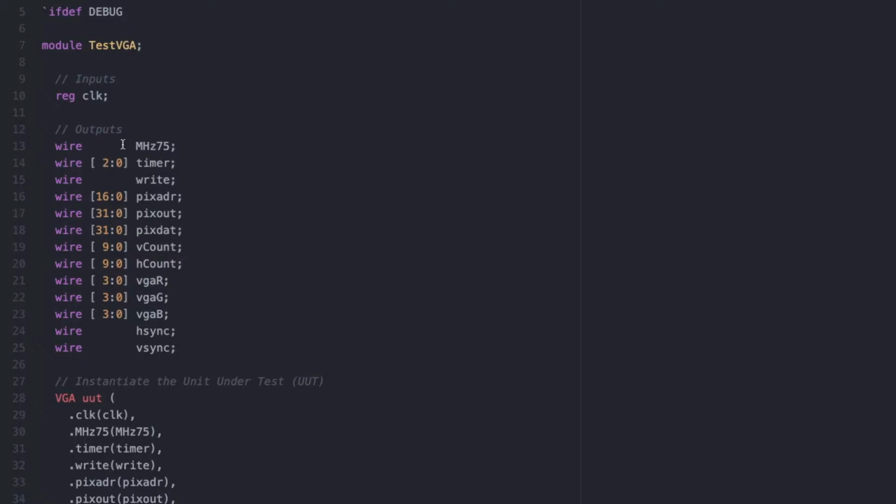And then timer, this just counts how many clocks per pixel. And then write, of course, I want to write data out to memory, and then I want to read it in when I'm displaying pixels. I just use write to initialize the RAM, and then it just cycles through the screen over and over, doing the same screen. And you'll see later that I initialize the screen so that it has an even-odd scan line thing. Basically, I took every permutation of the palette, 0 through 255, and I cycle through 0 through 255. And of course, that doesn't quite go evenly into 640 pixels. So every other line is interlaced, and you'll see the pattern.